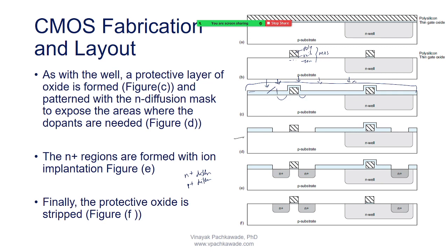So finally we come at the D, and then what we did, we took the wafer in the HF. We put the wafer, the oxide in this region where the mask was there, you see here we wanted the areas, the channels, that got etched, remaining oxide remained there, all over it remained there, only where we wanted N plus diffusion to be fabricated we got the access.